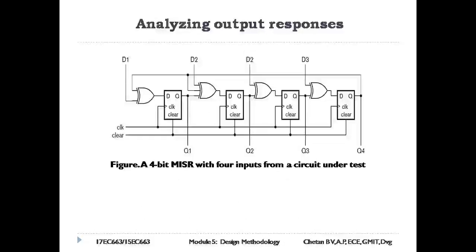Analyzing output responses. It is infeasible to store the correct output response for comparison with the circuit's output response. A commonly used technique for output response compaction is signature analysis.